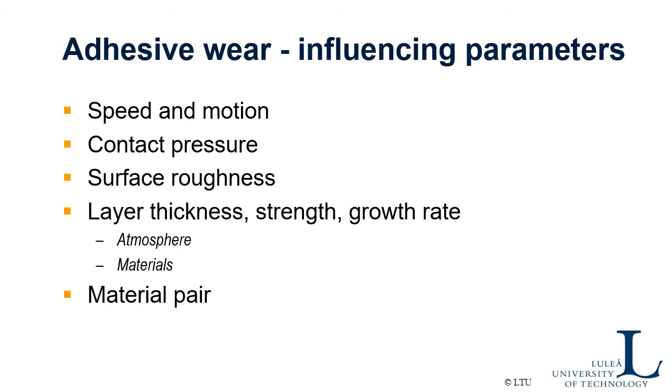The important parameters for adhesive wear are speed and motion. Normally the higher the speed is, the more heat, the more risk of wearing off the layers and creating a contact between base materials. The contact pressure, always bad. Surface roughness, well, if it's too smooth, as I said before, it shouldn't be too smooth. But if it's too rough, you may come into abrasive type of wear. So surface roughness is something to find an optimum for.